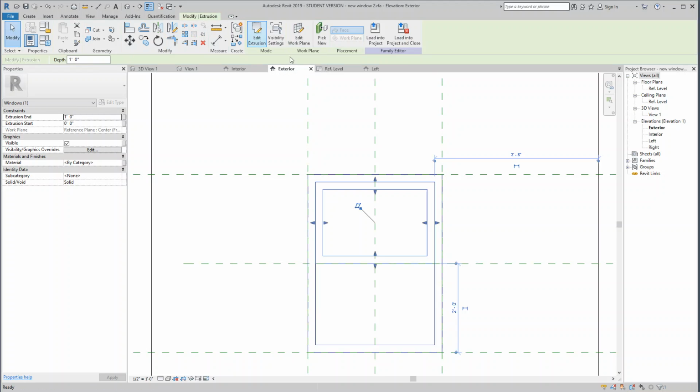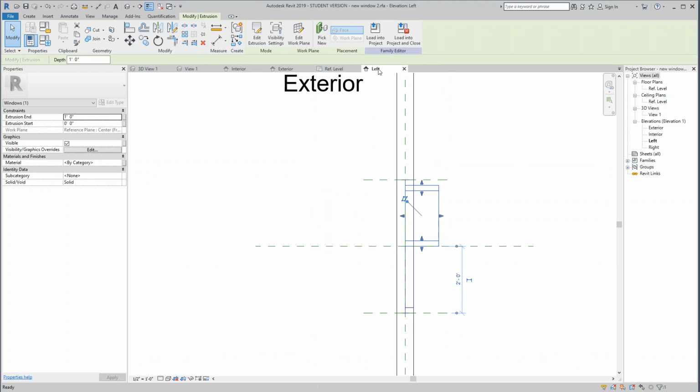And we'll complete that, and just as we did before, we'll look at that from the left side view. We want to make sure that it attaches to that front reference point. We'll lock it to that. And if we look over here at extrusion, we only want it to be about 1.5 inches deep. So I'm going to go 1.5 inches, and that should snap that down.